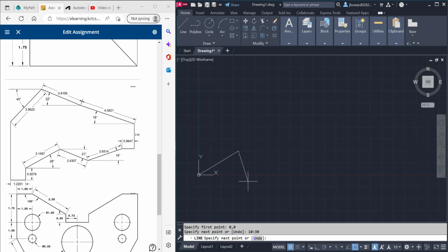Do you all see how that did that for me? It understood what that was. Now, if I was on that point, I'd have to use the at button to make this my new 0, 0, and I could do another 10 angle. That greater than is saying angle. And let's say I want to do 45, I can do 45 degree, and it puts it up. Y'all see that? That is the polar coordinate method.